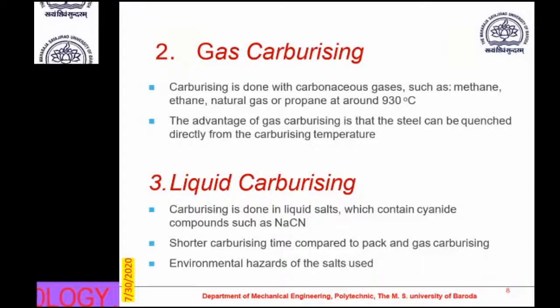Liquid carburizing. Here, the solution used is liquid, that is sodium cyanide. Shorter carburizing time compared to pack and gas carburizing. Environmental hazards of salts that are used, that is cyanide.